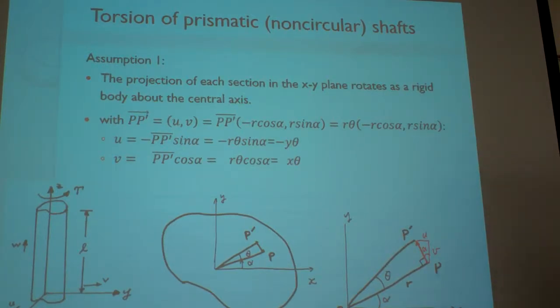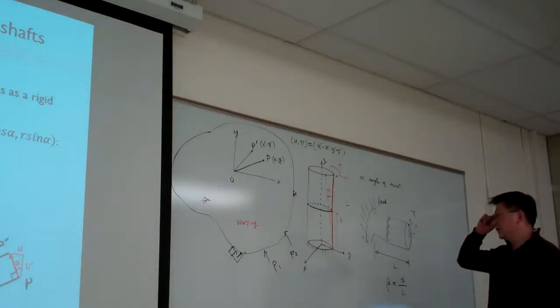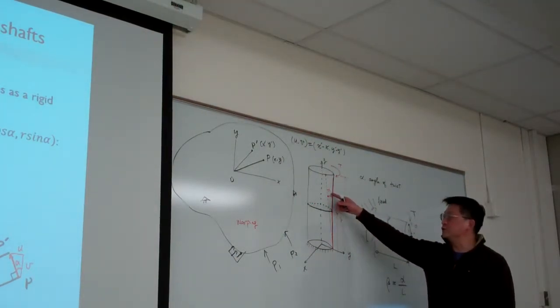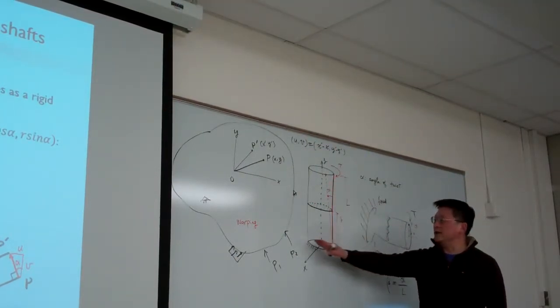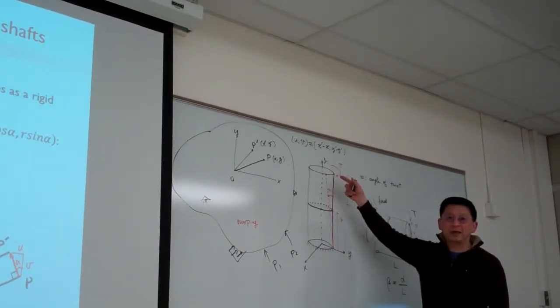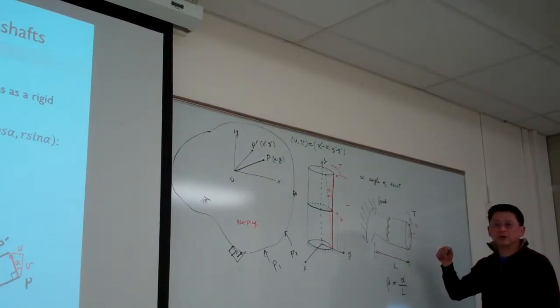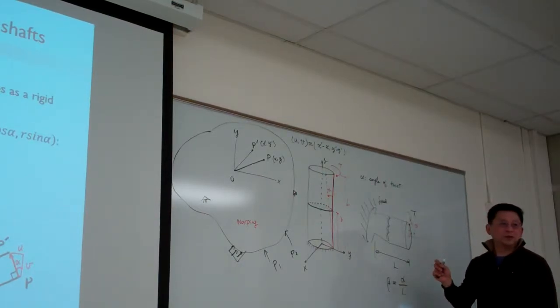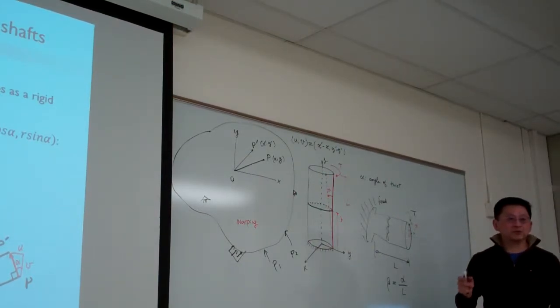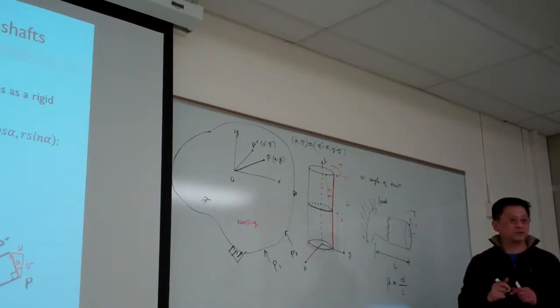Once we have everything ready, before I erase these portions: we know we have the angle of twist. Imagine we fix one end, then we measure the total deformation in terms of the angle from the other end. So alpha is one kind of measurement of how much the material is deformed. Shafts made of different materials under the same loading have different angles of twist.